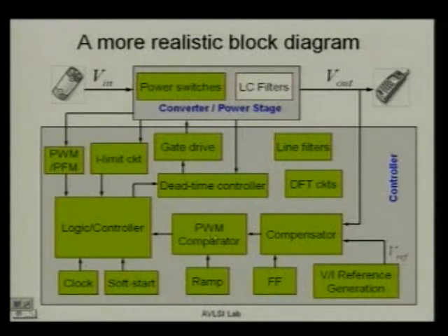Then there is the PWM comparator. Something called logic controller. Why is this required? This is required because, other than controlling your system dynamics, you will have to take several actions like switching off parts of your circuit when you are in standby. A mobile phone, most of the time it's in standby, it will draw large current only when you get a call.